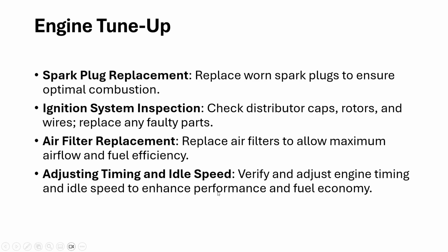Adjusting timing and idle speed: verifying and adjusting engine timing, checking whether the timing line is proper when ignition is happening. That has to be checked, and idle speed must be tuned to enhance performance and fuel economy.